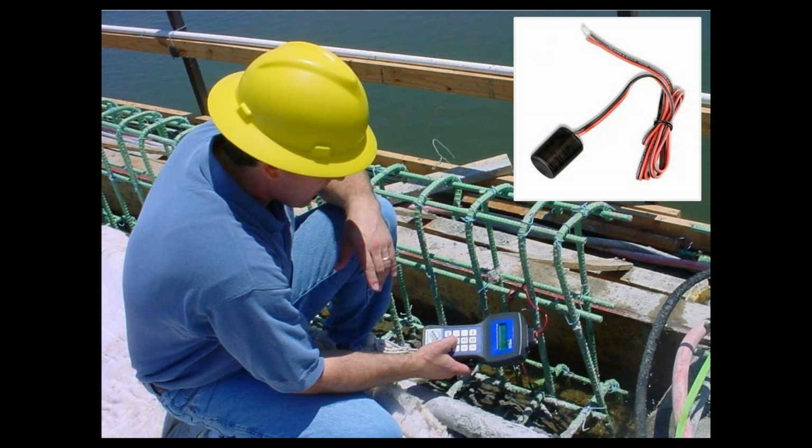In most cases, you can simply embed a temperature sensor inside the concrete. This could be as simple as a thermocouple that you put in the concrete in the field. You can drag one end of the cable outside the formwork, connect a data logger to it, and basically record concrete temperature as it's cured in the field. Or you can use maturity loggers like the one that I'm showing here.